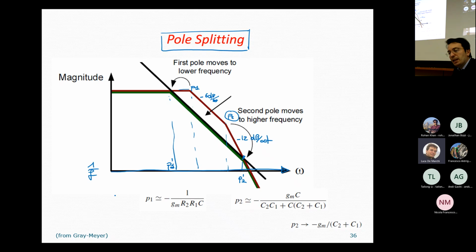So basically, we have to take into account the fact that when we pull down the voltage at this point, the VSG increases as well, and the VSG of transistor 6 has a quadratic relationship with the current which is flowing in the same transistor. So when we pull down the voltage here, the value of I6 increases very rapidly.